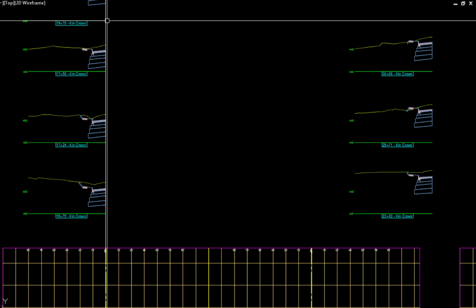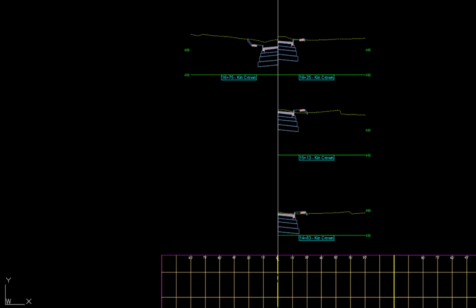Driveway section views should remain in correct ascending station order along the vertical line. It does not matter about the vertical spacing between the section views at this time. For this video, the Kincaid Drive Right profile section views have been created and are shown in a column that has been combined with the Drive Left profile section views.